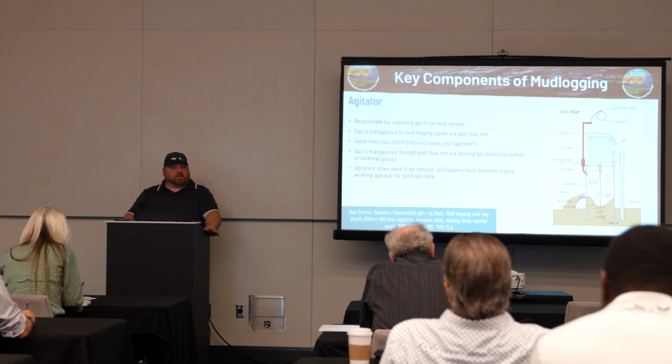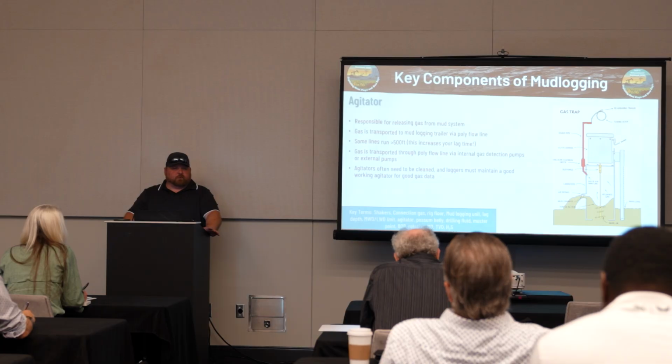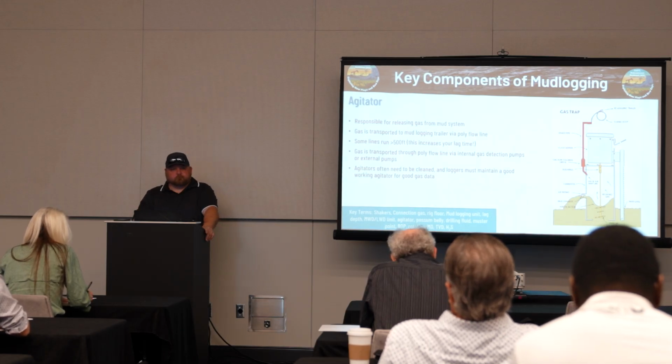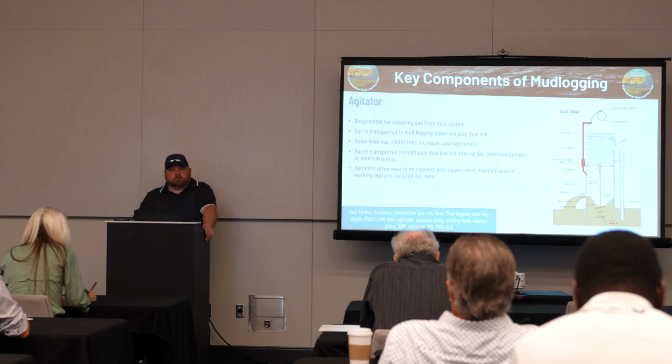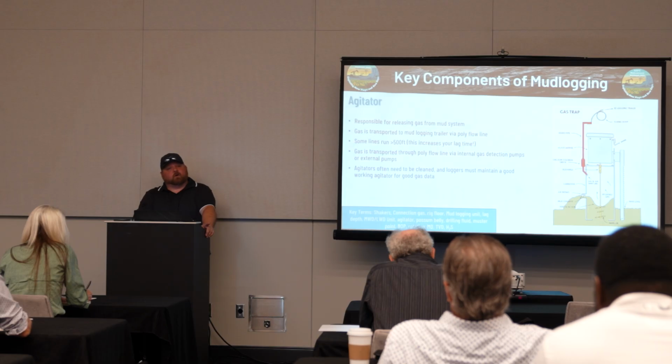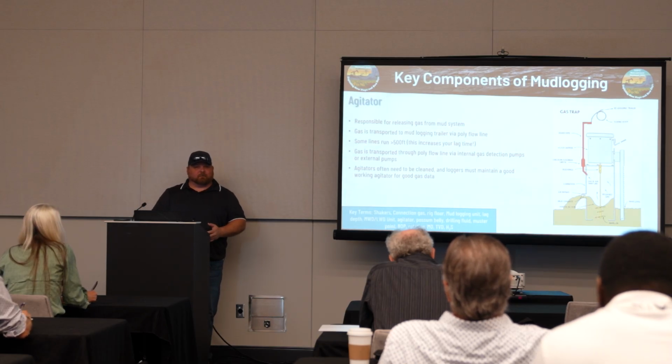I've seen 1,000 foot of polyflow take 3 or 4 minutes with brand new pumps. So yeah, you would add that into the lag time, assuming there's no dilution through cracks or anything like that, obviously. Yeah, that's actually a good point. That's where your bump tests and all that come in handy.